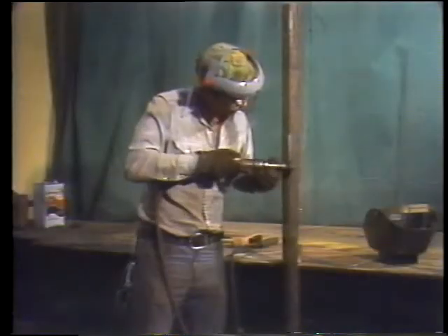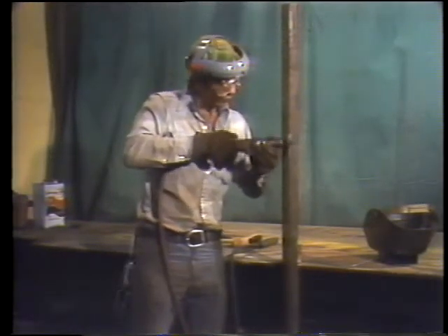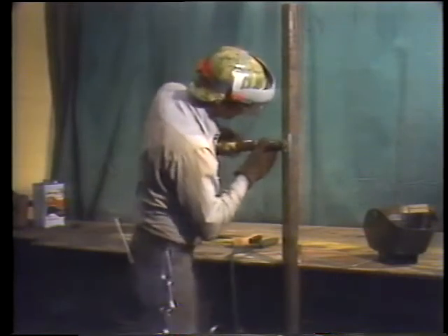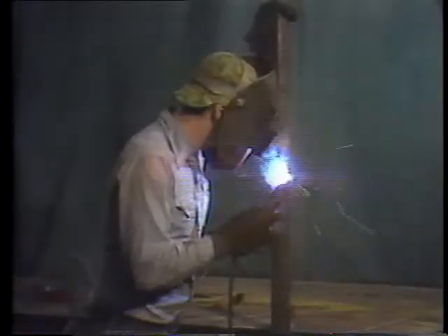Clean the area to be clad so it's free of rust and other deposits. Hard deposits or irregularities on the tube must be removed by grinding. The tube should be ground down until the surface is bright. Next, weld metal is applied to the damaged area.